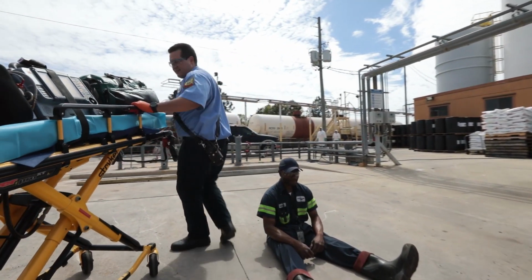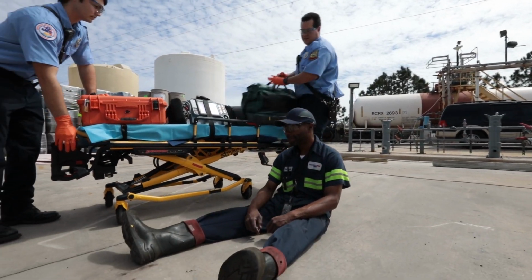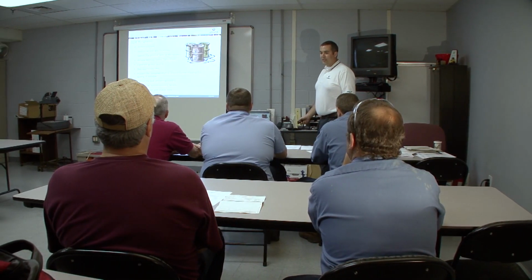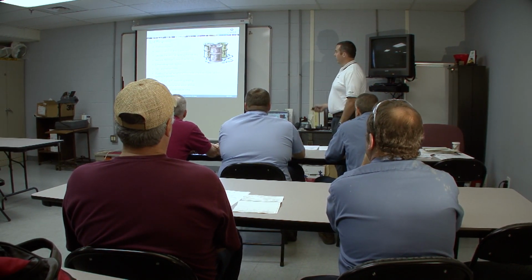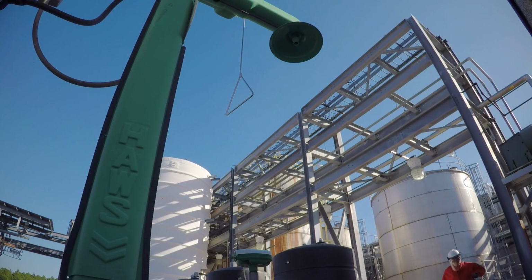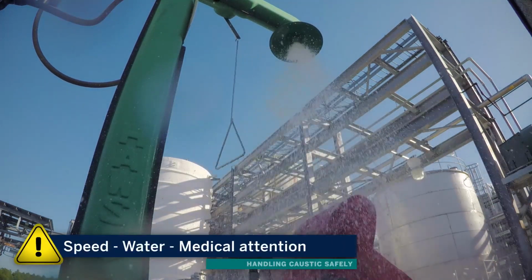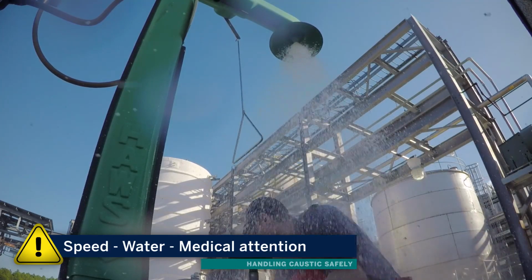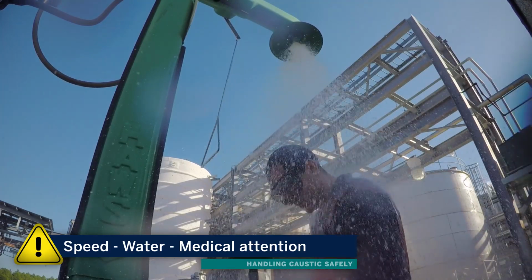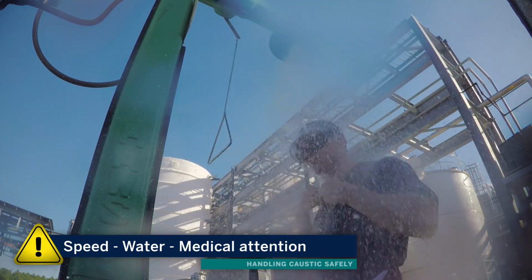Sometimes even a well-trained and well-protected operator can accidentally be exposed to caustic. Proper training in first aid procedures is important when working with caustic solutions. There are 3 important points to remember when dealing with caustic solution exposure: speed, water, and medical attention. The sooner caustic is flushed off the skin or out of the eyes with water, the less chance of a chemical burn or permanent vision damage.